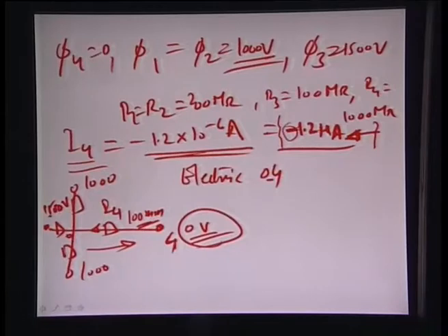Another issue is that we also need to determine the electric field in the longest channel. If you may recall, the longest channel is the one between O and 4, and it is about 100 millimeters in length. So the electric field between O and 4 is the voltage between O and 4, which is phi 0 minus phi 4, divided by the length of 100 millimeters. We can calculate the phi 0 minus phi 4 value easily as I4 R4.